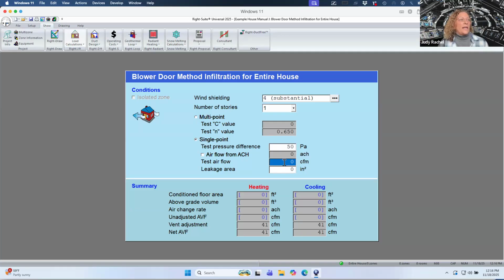And when we did the blower door test on this house, the CFM50 number was 281. And you'll see that a bunch of math was done already, because this is what the load calculation procedure is really drilling down to: an equivalent leakage area in square inches. So that's what that leak is. And you'll see that the ventilation that I put in, that exhaust ventilation, has shown up down here on this screen as well. So that's our infiltration screen.